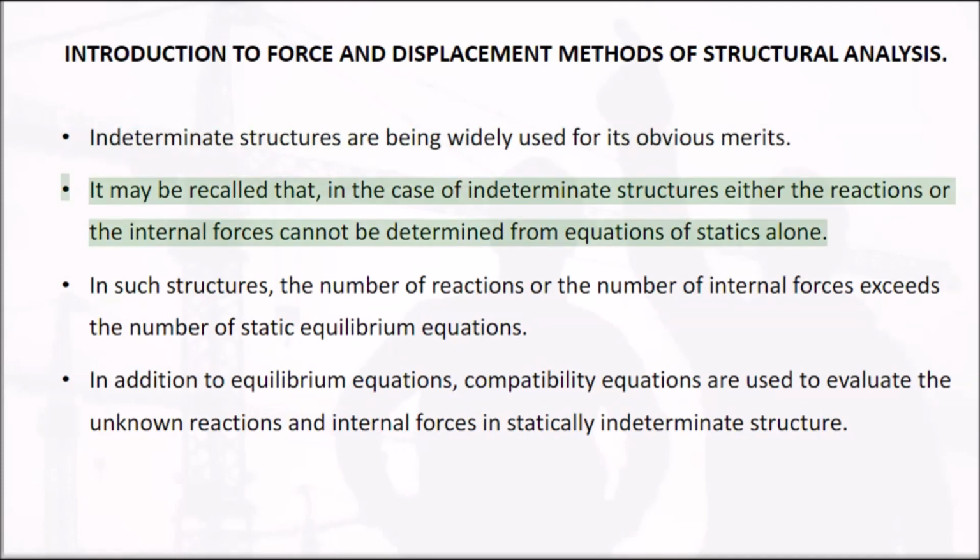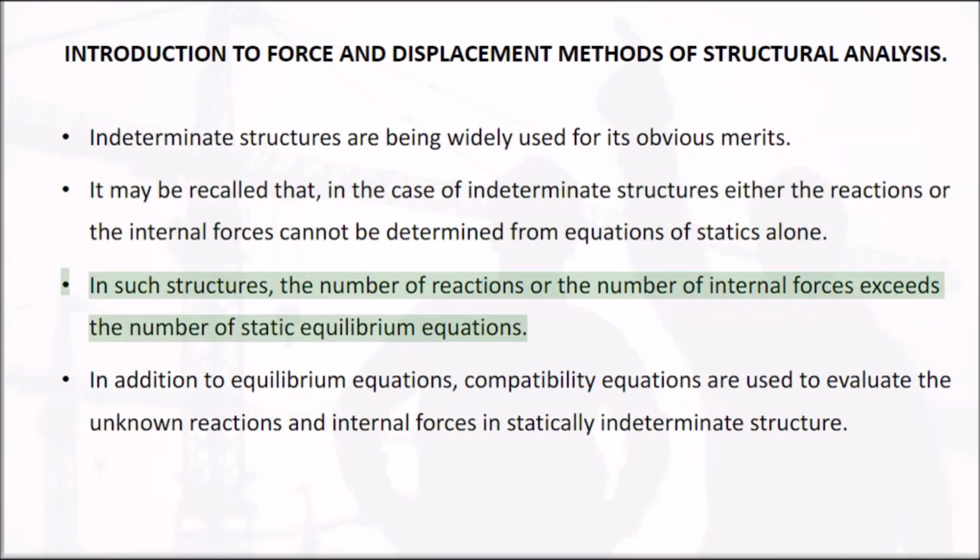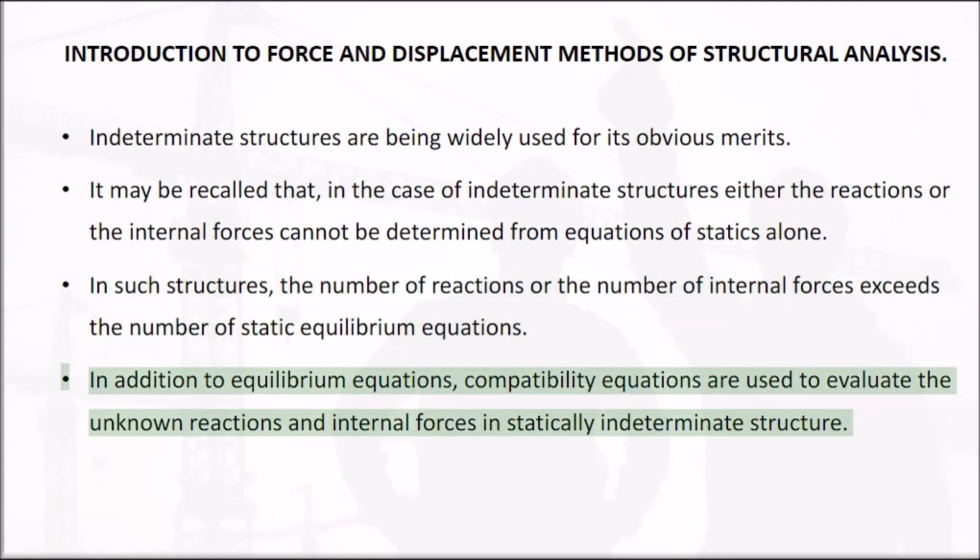It may be recalled that, in the case of indeterminate structures, either the reactions or the internal forces cannot be determined from equations of statics alone. In such structures, the number of reactions or the number of internal forces exceeds the number of static equilibrium equations. In addition to equilibrium equations, compatibility equations are used to evaluate the unknown reactions and internal forces in statically indeterminate structures.